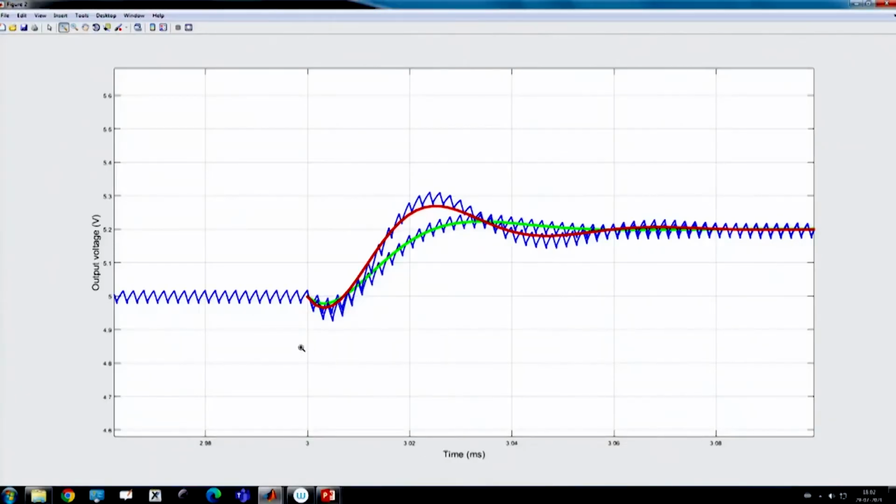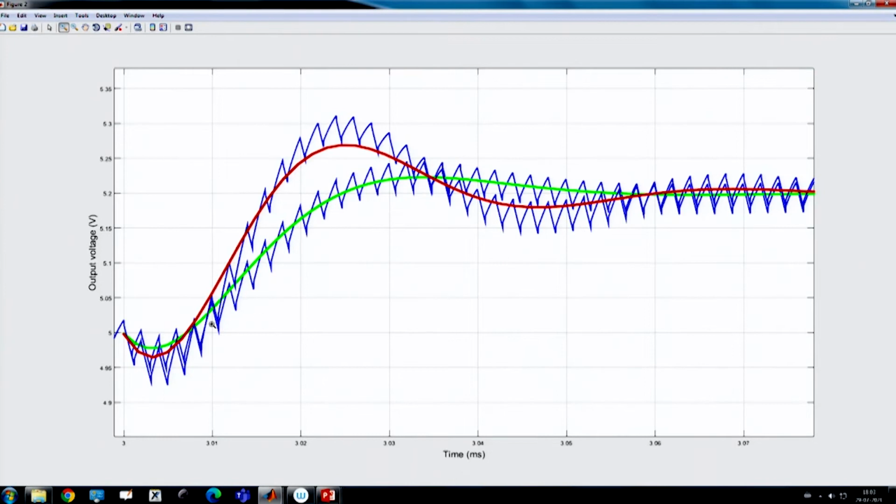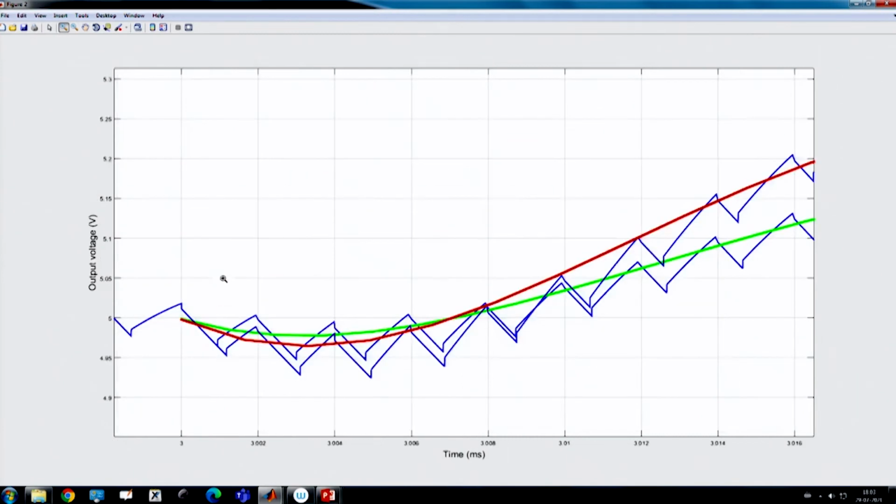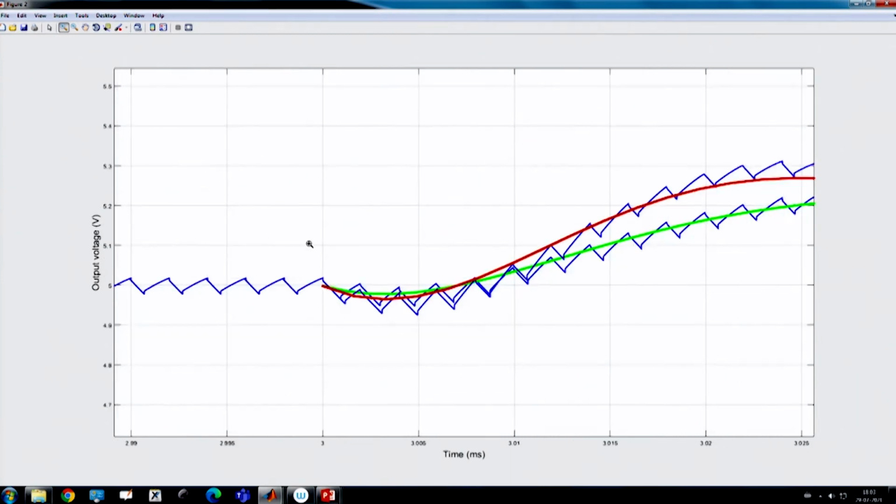So, this is a comparative result. The red one is where we want to increase the bandwidth, but the penalty is that the overshoot becomes higher, and it is very high, not acceptable. Maybe your settling time will be more or less the same, but the overshoot is unacceptable. Another thing, you may have some additional right half plane zero because you are trying to push the bandwidth.